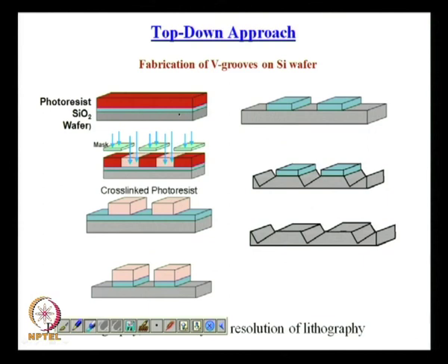Okay. So, there will be some portions of the photoresist which would be cross linked, which would be hard in this specific case, the rest will remain as it is, which would be easier to dissolve away using the right choice of solvent. So, now you have islands of photoresist, you now remove the oxide layer as well.